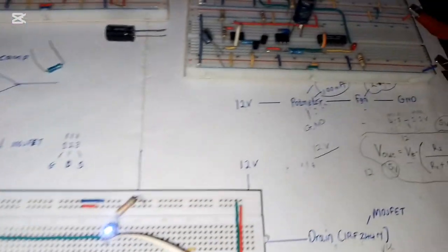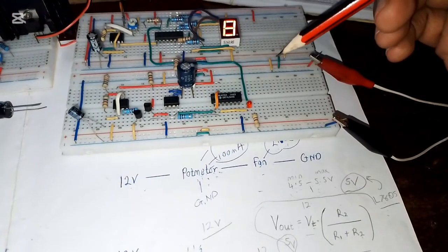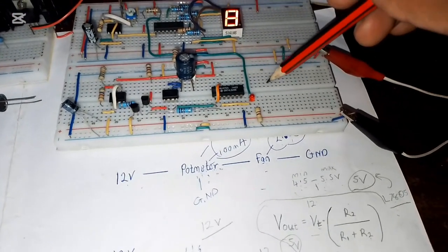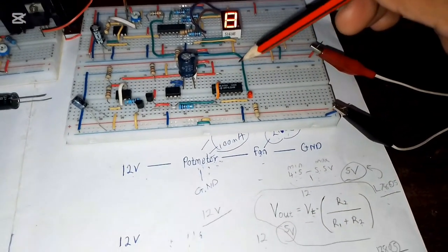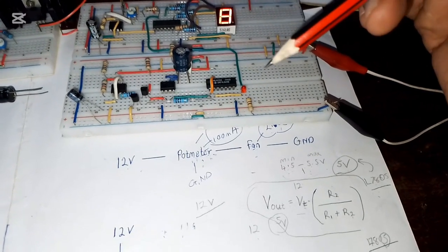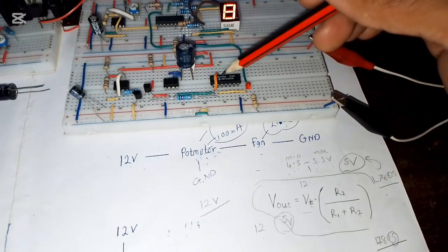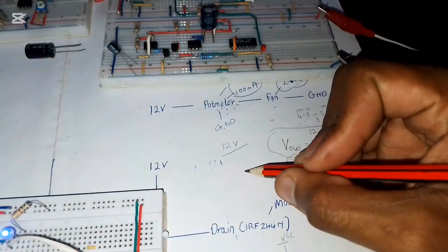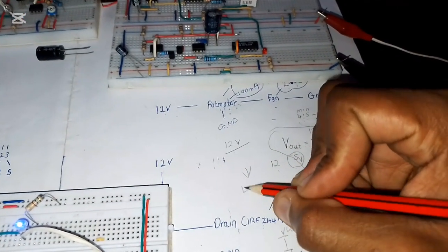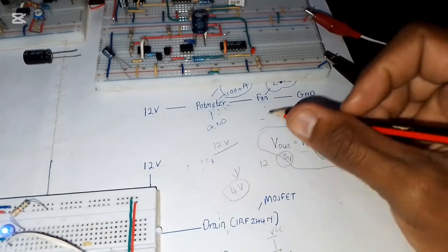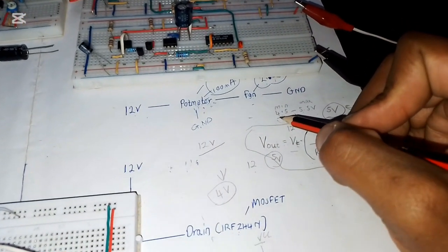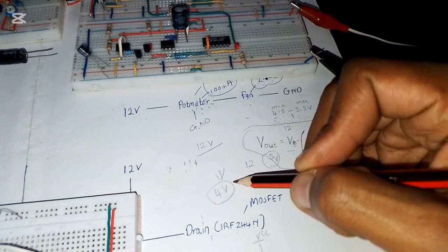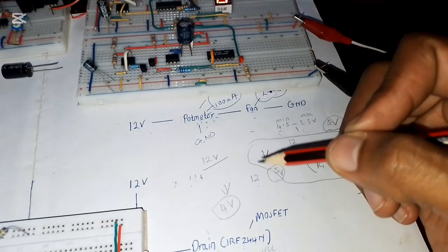And this is the issue that I've considered, and I've seen that I'm not going to use a voltage divider to power this IC because the IC will draw current, of course, and once it draws current, it means that the voltage from the voltage divider is going to change. Most probably it's going to drop, and it can drop all the way to 4 volt, which is not ideal to power the IC because the minimum is 4.5. So it means that you can damage the IC just by doing that.